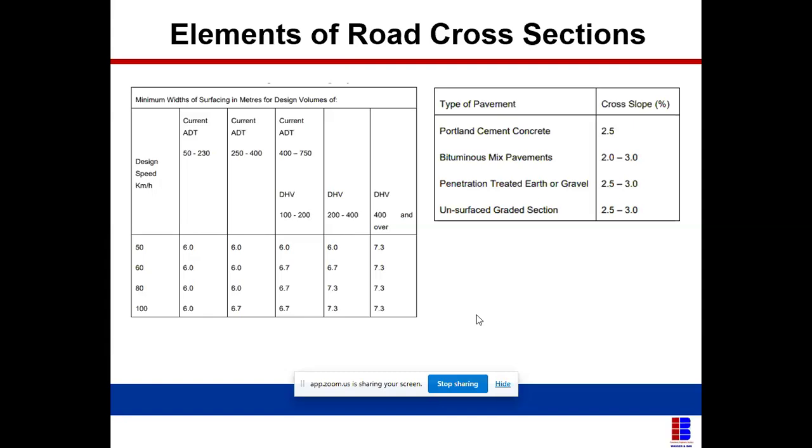If you create the road design for me, let's say I'm a consultant and I want to vet your design, to checkmate what you've done, just like how we do for structures. What I'll be looking at: 1, the gradient of your road. 2, the curve parameters of your road. 3, the K values, and the length of your tangent and all of your road. So for a paved surface, if you're having a gradient less than 0.3, the design needs to be flagged. The gradient is supposed to be minimum 0.3 to maximum 8%, 6%, depending on the vehicles that are plying that road.